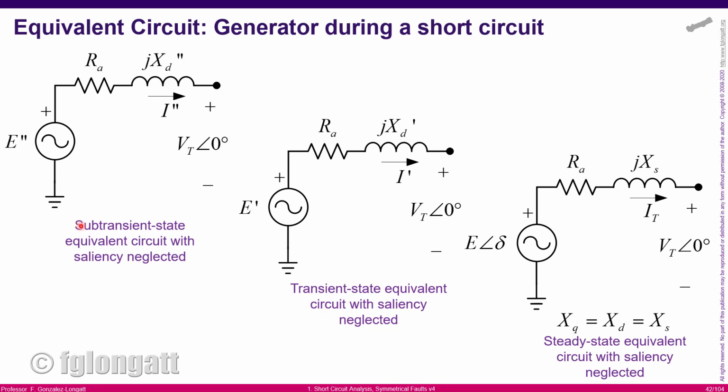If you are using the full differential equation, you will get the full picture about the short circuit. You will get the beautiful wave that represents the short circuit. What is the problem? In practical terms, that is not useful for short circuit analysis in big systems. We can do that using software, for instance, EMT simulations using PowerFactory, but it's not typical. Probably if you are working with new low carbon technologies using power converters, you need to see the full wave, the time domain representation of the short circuit current.